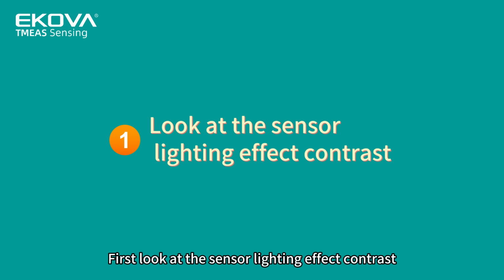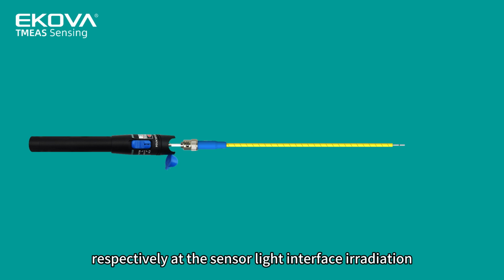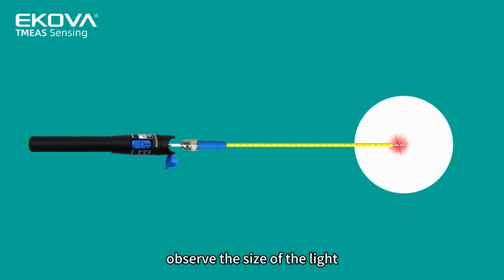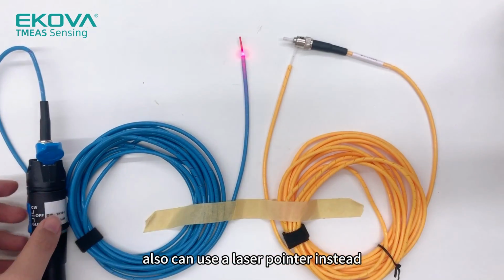First, look at the sensor lighting effect contrast. Prepare a red light pen and irradiate the sensor light interface respectively. Observe the size of the light spot coming out of the sensor probe end. For a more visual display, I prepared a tool, but you can also use a laser pointer instead.